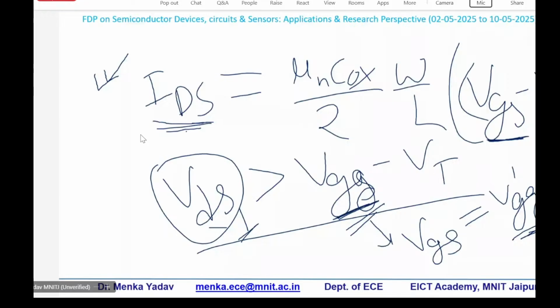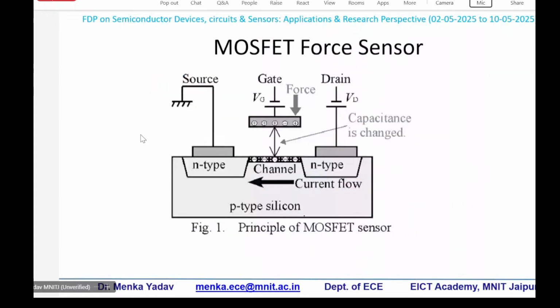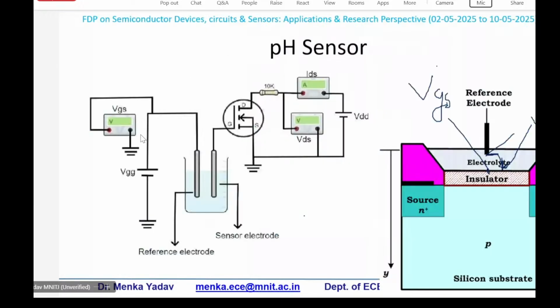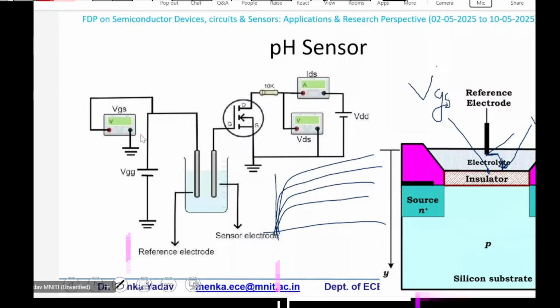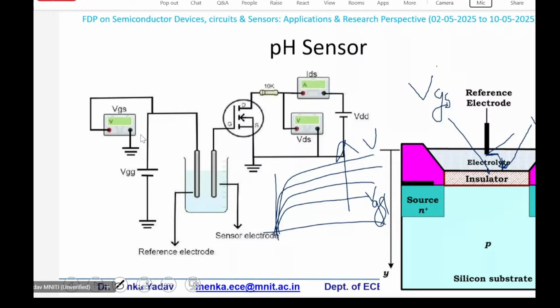You can see it in the IV characteristics. These are the output IV characteristics. Since we have done it in the saturation mode, you are going to get a higher amount of current according to how much your VGS is getting changed. If VGS is increasing, this is the lowest VGS value, and then it increases in this way, say VGS 4, and that is going to increase the current. VDS was fixed, so you are somewhere at some place, and this is ID.